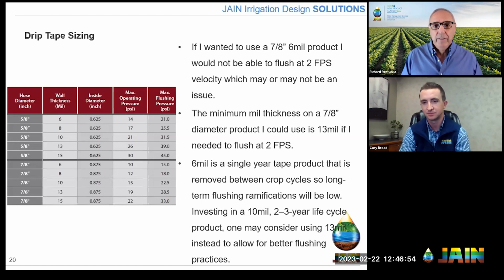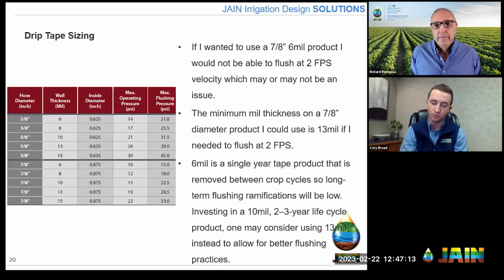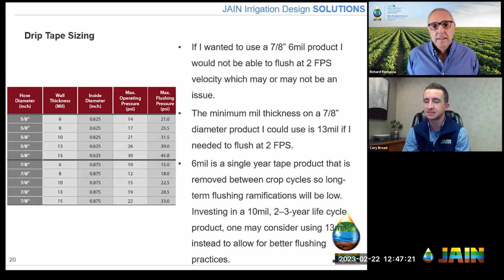Thank you. So we have another viewer, and he's asking about drip tape and emitter line. And your chocolate milk picture looked like this was buried. Can you go subsurface with any of these products? Absolutely. So if I back up to the Amnon and Top Drip, those come in anti-siphon standard. So it has anti-siphon, anti-suckback technology built into it.